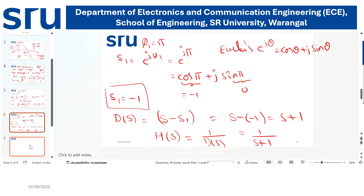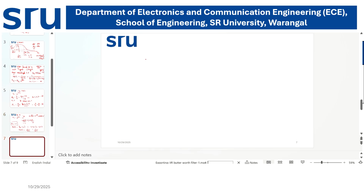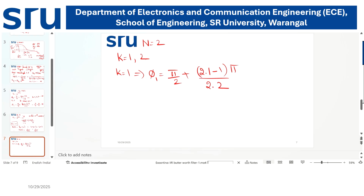Suppose the order of the filter is equal to 2, then the k values are 1 and 2. If k is equal to 1, then phi 1 is equal to pi by 2 plus (2 into 1 minus 1) divided by (2 into the order of the filter, 2) into pi.